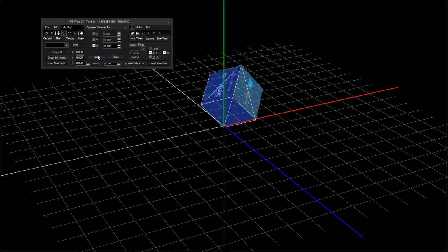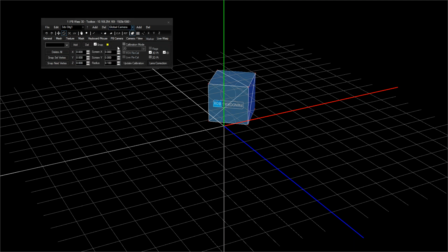You see, it has nothing to do with the 0 point we set up in Blender anymore. So that's a difference between Pandoras Box and the Warper. Pandoras Box will not ignore the pivot point we have set up, but the Warper will ignore it and use the own local 0 point of the 3D object.